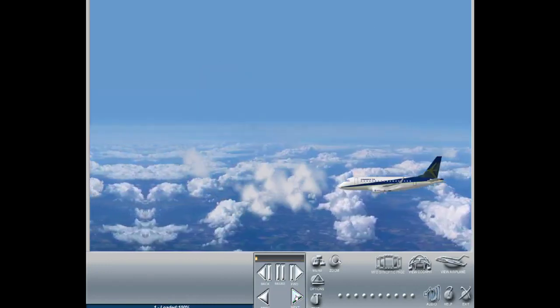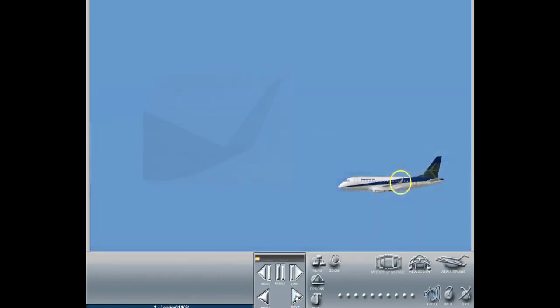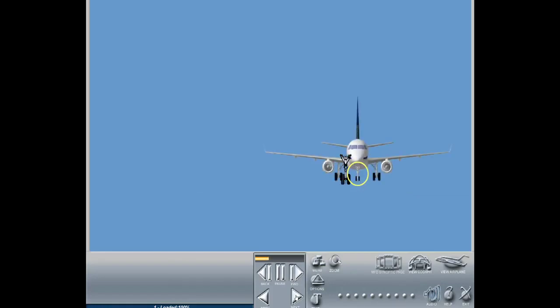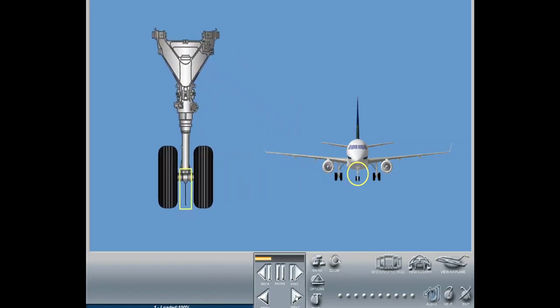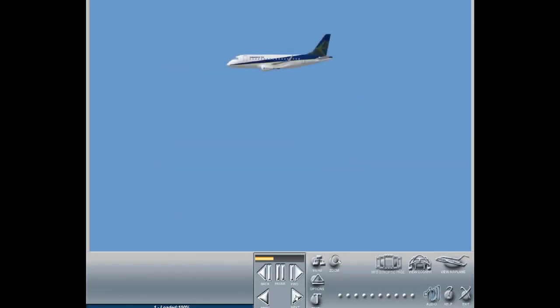The static discharge system offloads static electricity from the airframe to the atmosphere while the aircraft is in flight and offloads static electricity to the ground when the aircraft lands. In flight, this prevents the dangerous effects of lightning discharges and decreases the interference on the radio communication and navigation. On ground, this system minimizes the risk of electrical shock to crew, passengers, servicing, and maintenance personnel.